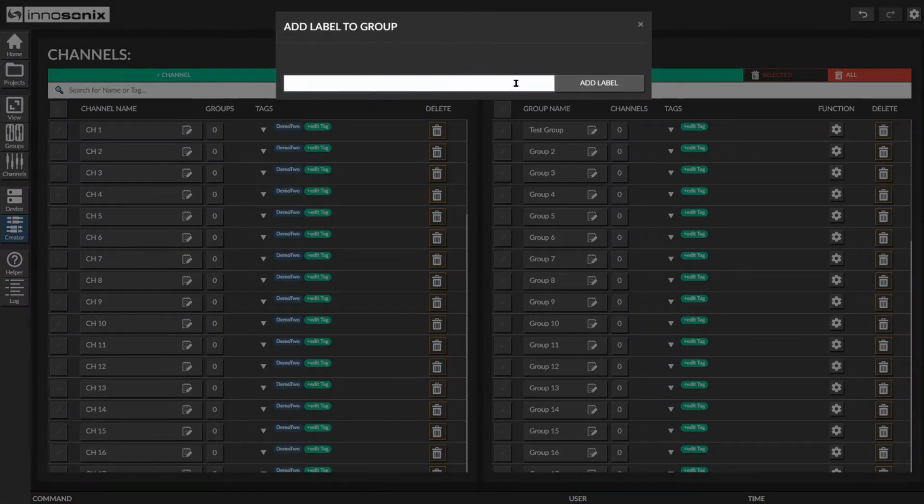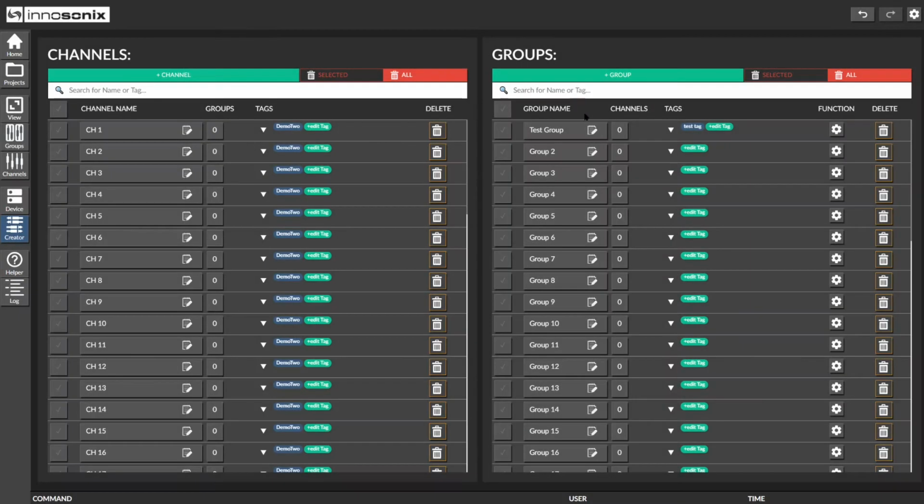Please note that Maxx-Remote also automatically sets and changes tags. For instance, when assigning a channel to a group, the group will receive the channel's name as a tag and vice versa. Changing the name of one of those linked objects will also update the corresponding tag to the new value. The same goes for project channels and devices. Linking a channel to a device will add the device's name as a tag to the channel and the channel's name as a tag to the device.